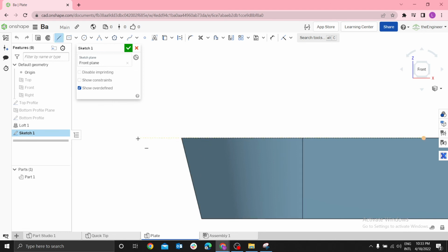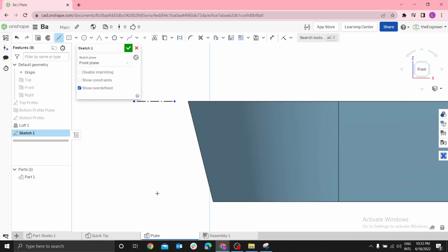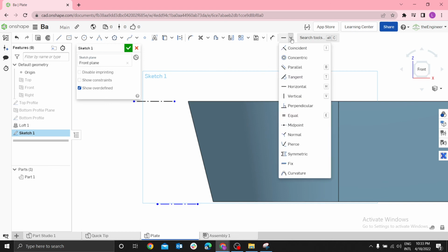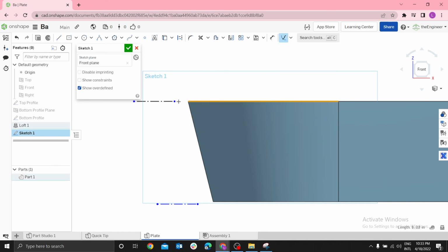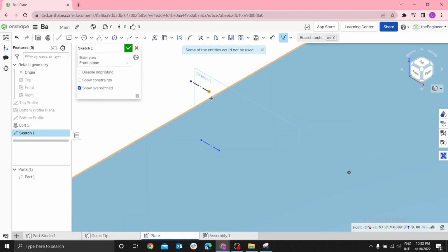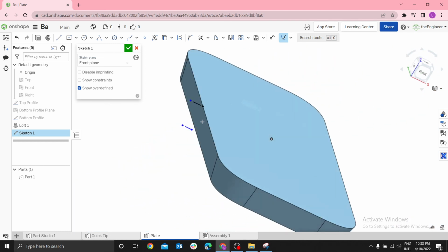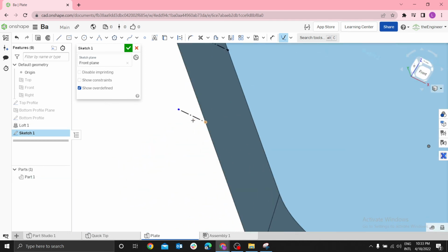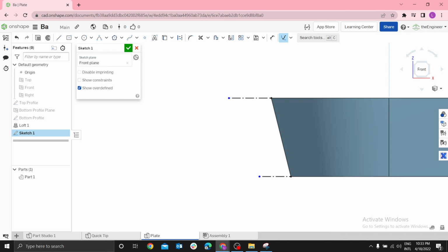Therefore, you select a line, you press Q, L for line. You can always press Shift Enter to repeat your previous command. Q for construction. Therefore, you select pierce edge to this line, this point. The best is go isometric because I want to pierce this to this. Same case applies this to this. Then N to go back normal.